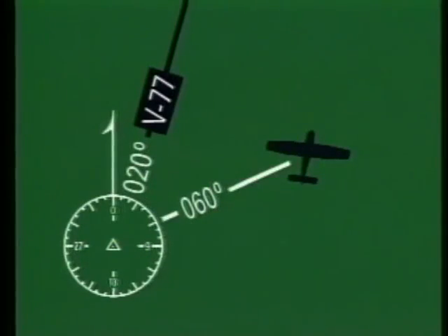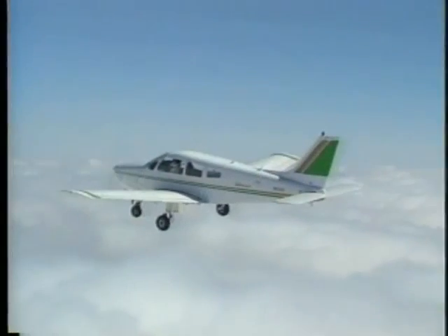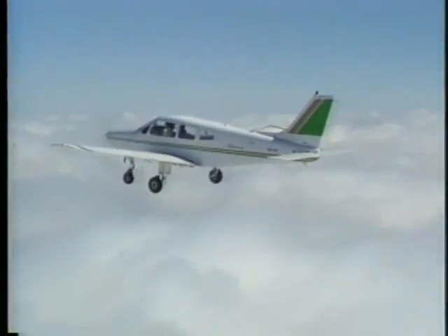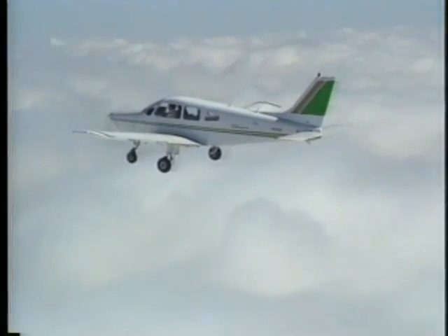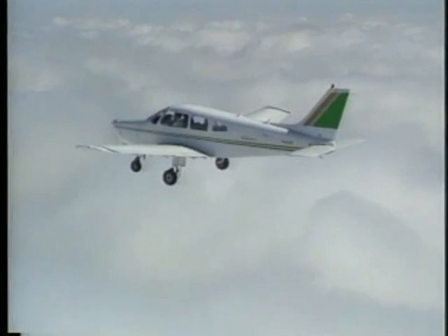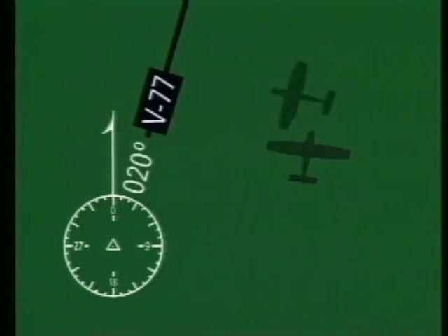Now that you know what radial you're on, you need to choose a heading that will enable you to intercept the 020 degree radial. The angle of interception depends on several factors, such as your ground speed and proximity to the radial and navigational aid. A wide range of angles may be suitable. One possibility is to fly a 90-degree intercept to the 020 degree radial. In this case, you need to anticipate your turn onto the airway, since a 90-degree standard rate turn takes 30 seconds.